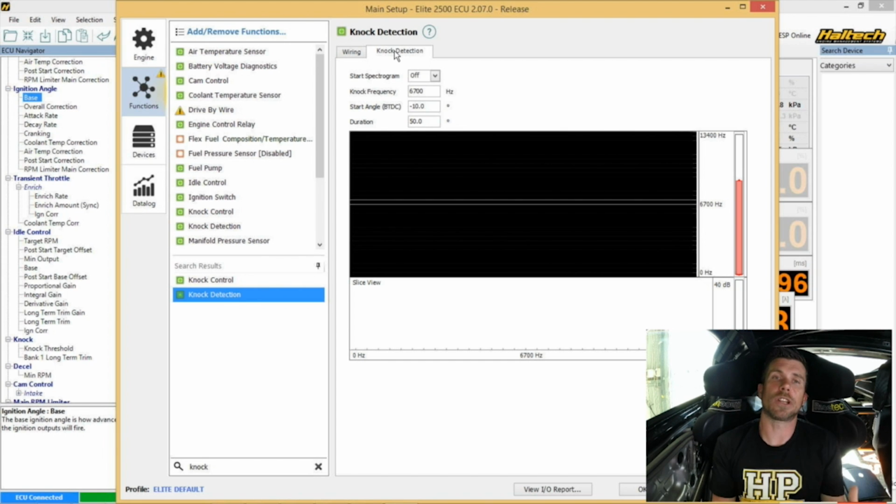So of course you've got a lot of noise going on inside the engine. The engine is a mechanically very noisy place, and in order to give the knock detection system the best chance of detecting knock and ignoring all of that other background noise of piston slap and bearings and valve train noise that we perhaps don't care so much about, we can use the knock detection system to focus specifically on the frequency that knock is occurring at.